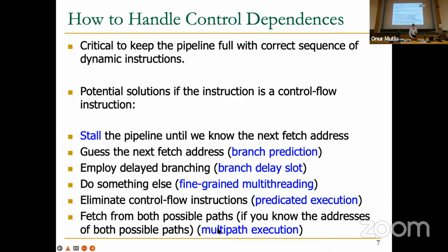Okay, so this is a bad idea if you always do it, but these ideas could actually be very useful if you do it very selectively. Meaning, I have no idea how to predict this branch. It's very, very hard to predict. I have all known methods implemented in my processor, and I still cannot predict it. So let me take 2 paths on this one. I don't do it for every branch. I do it very, very selectively for key branches. Then you may actually win.